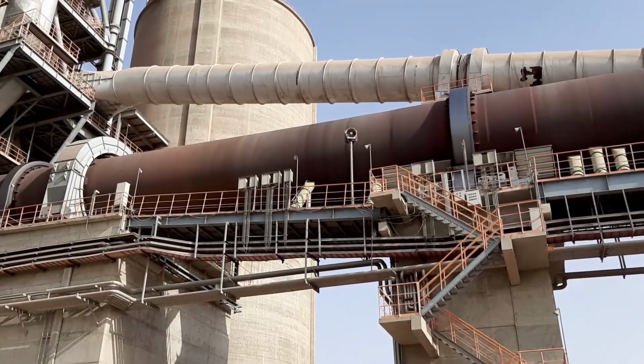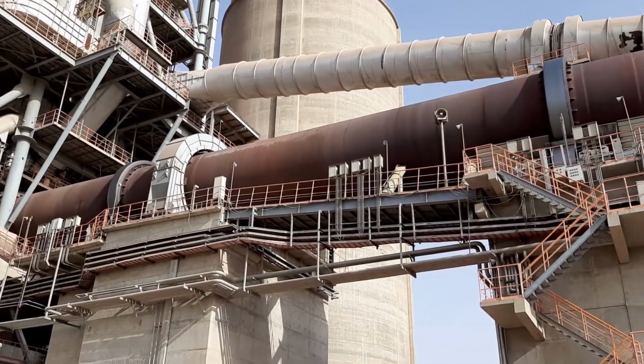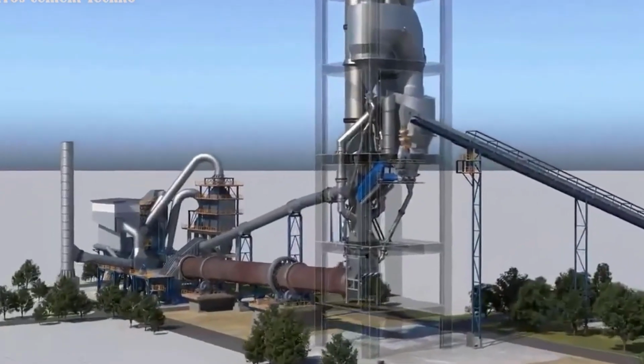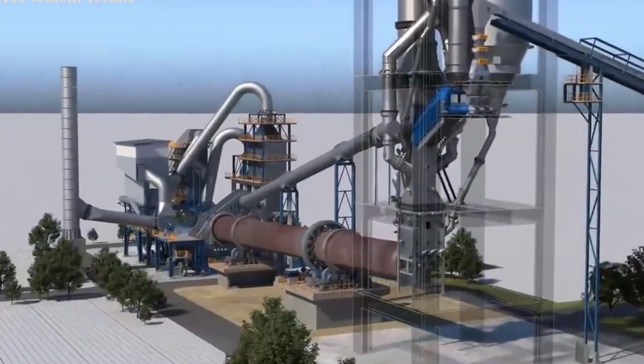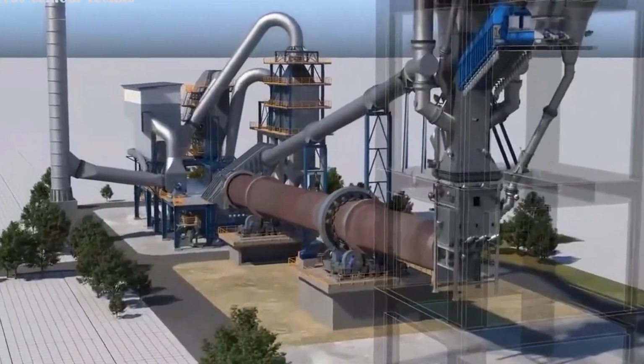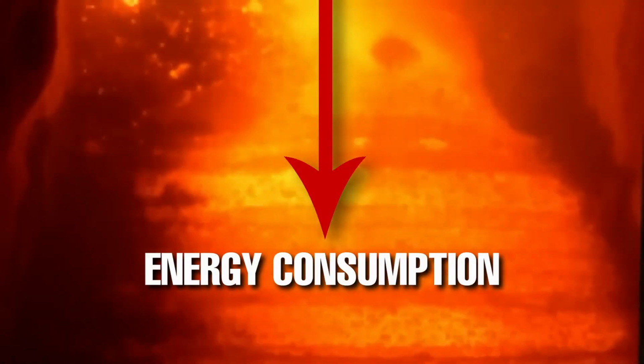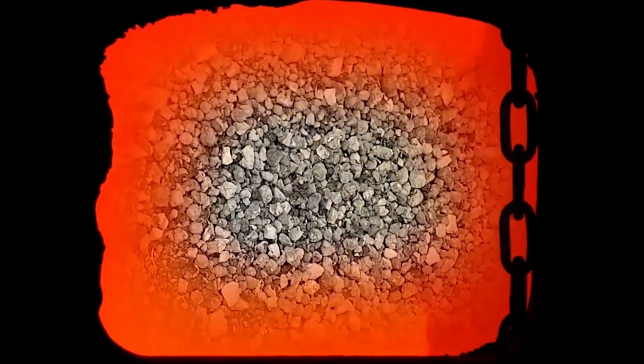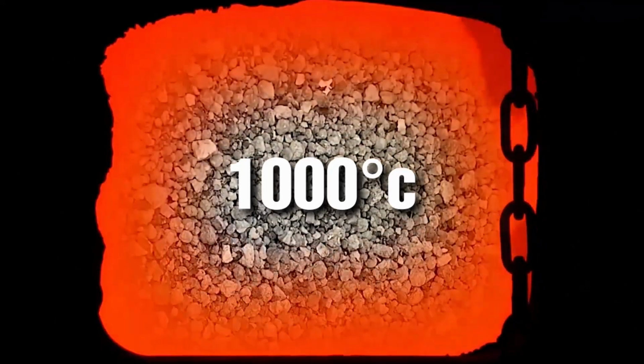The process of heating the raw meal involves several steps. Preheating. Hot exhaust gases from the kiln are used to preheat the powdered raw meal before it enters the kiln. This preheating step helps to reduce the energy consumption in the kiln. Calcination. The raw meal enters the kiln at temperatures of around 1000 degrees Celsius.